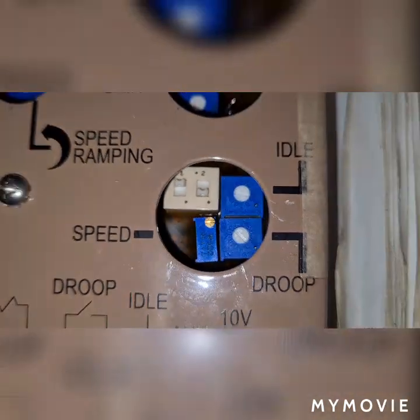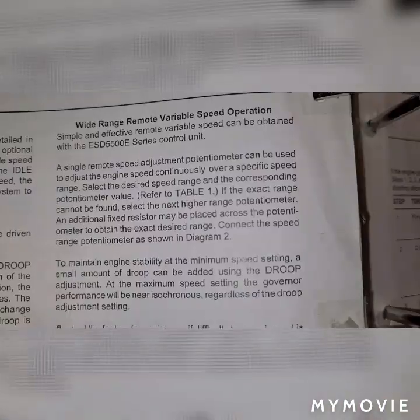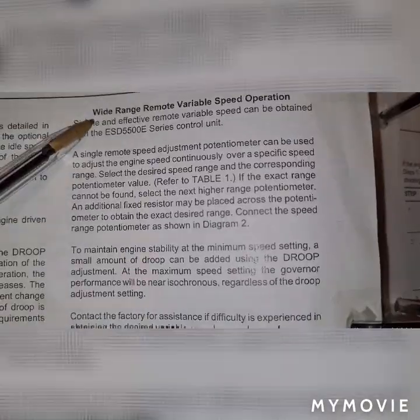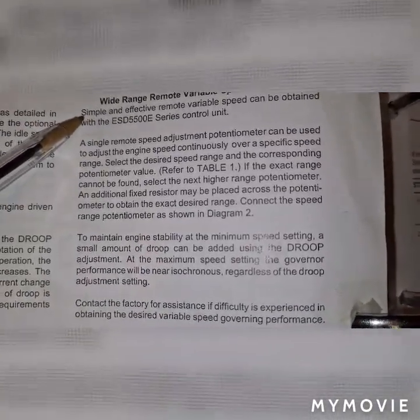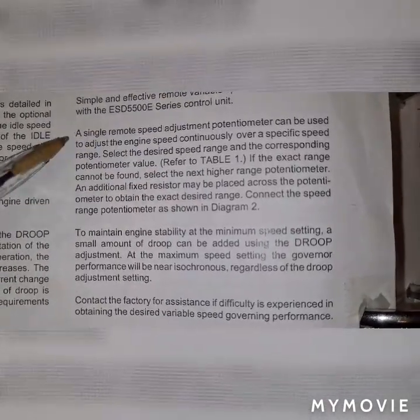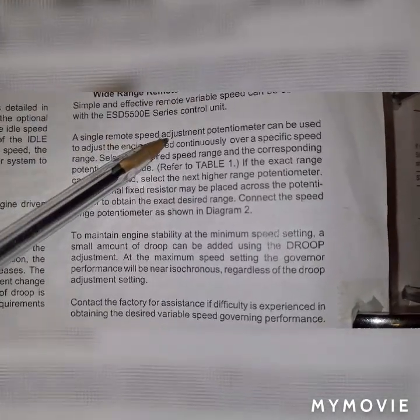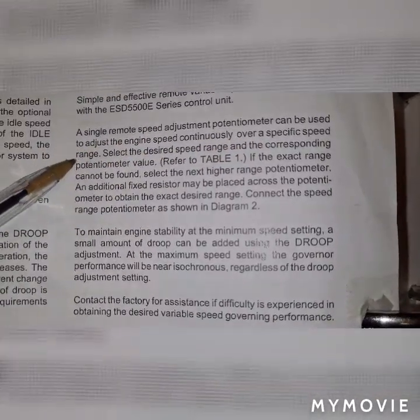So what we have also is the speed. This is the most important one, the speed of your generator. So in here you will read: wide range remote variable speed operation. Simple and effective remote variable speed can be obtained with the ESD 5500E series control unit. A single remote speed adjustment potentiometer can be used to adjust the engine speed continuously over a specific speed range.